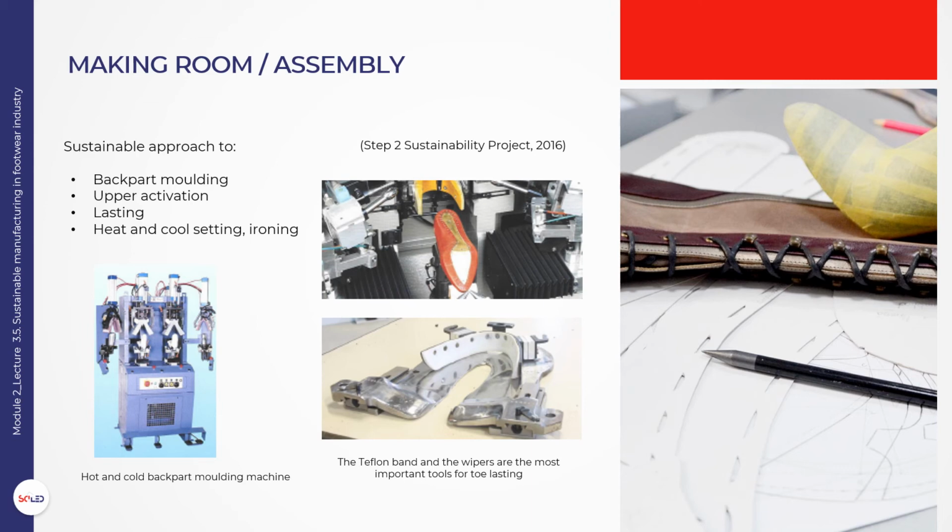The keys for not having reworks or rejects after lasting are choosing the most appropriate components, good technical design followed in cutting and stitching, using standard profiles and perfectly adjusted tools, choosing the appropriate lasting machine, and the glue application method. Today, hot melts are increasingly being replaced by water-based adhesives.